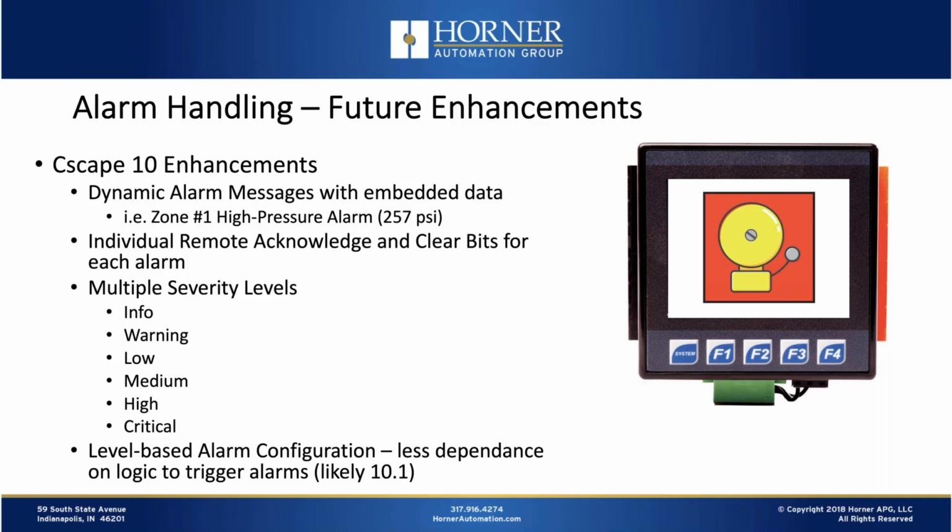So every alarm we have today depends on a trigger bit. And if you're just looking for a value to exceed or be below a certain threshold for, say, an analog value or a floating point value, you still have to put in some very simple ladder logic, or IEC logic in the case of IEC, to effectively trigger that alarm condition.